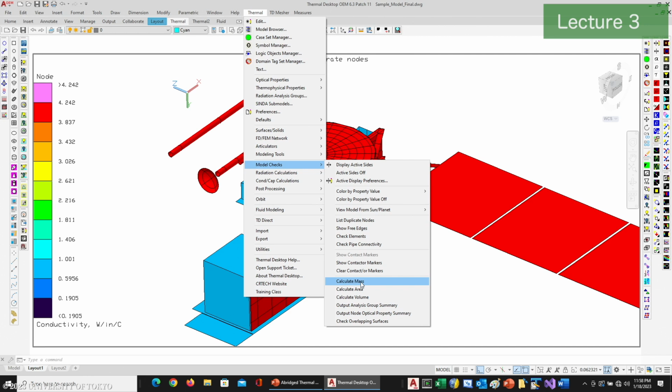By and large, our thermal models tend to underrepresent mass. Usually that's okay because we're more worried that if there's too much mass, it will dampen out anything. If we're trying to be stable, we don't want to overdamp the system. We'd rather underdamp the system. If it responds too fast and it's still within requirements, we're okay. But there are some times that you might have to worry if you had a control system that didn't respond properly, if you were too light. That might be something to do.